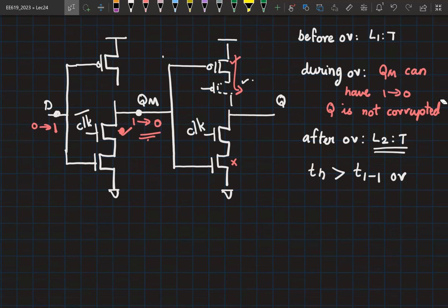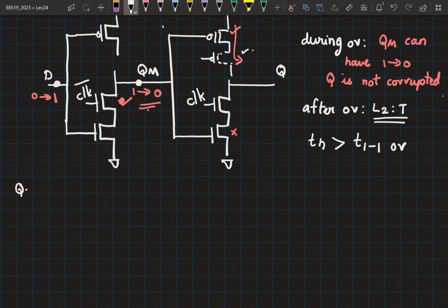Okay, so far we have been dealing with dynamic latches where both clock and clock bar were involved. Can we construct a dynamic latch which uses only one phase of the clock? No clock bar. I want a latch, but I don't want to use clock bar in my circuit. I only want clock. We can have a pre-charge and evaluate type of phase. Okay, so let me give you the architecture, but before that, let me give you some homework questions.